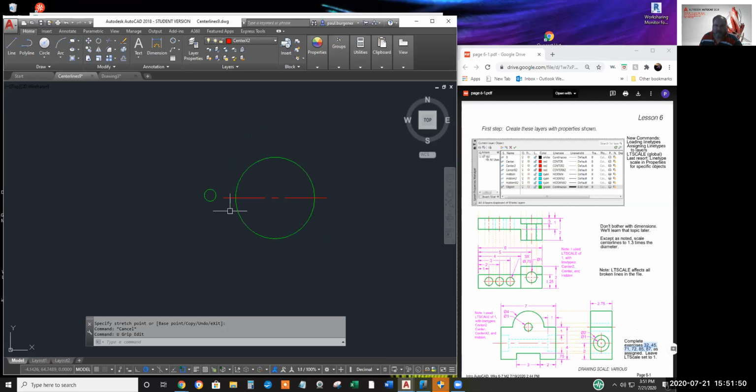Now notice, these two circles I scaled by a factor of 2 in order to use the 3 line types. So you change the center to the short or the small circle line type. I'll scale it by a factor of 1.3. And then I'll mirror each to get the bullseye.